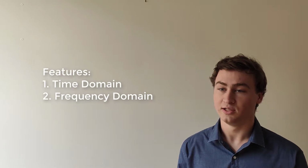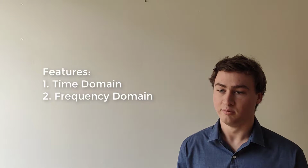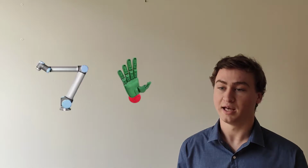Features are then extracted from the recorded signals. These features were from the time and frequency domain and are needed to be able to discriminate between the different positions that make up the dataset. The feature sets were used to train a supervised machine learning classifier, such as linear discriminant analysis and support vector machine classification algorithms. The goal of this project was to have a real-time testing of the classifier's performance and to use the classifier's output to move the robotic hand or arm.